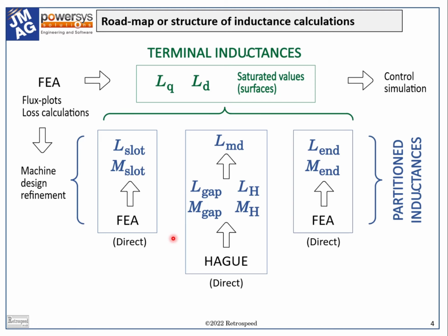And this remains the case even today with very advanced winding manufacturing methods such as the hairpin winding, which must still satisfy the classical rules and is still characterized by the same winding factors. And much of this theory is couched in terms of integer arithmetic, and none of it can be found in finite element analysis software.